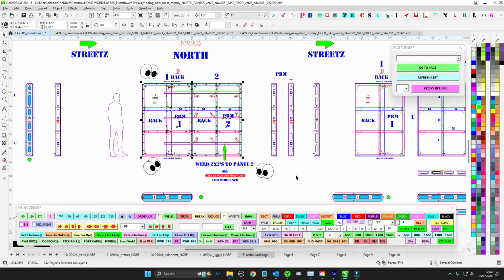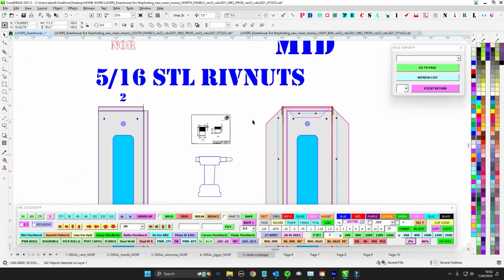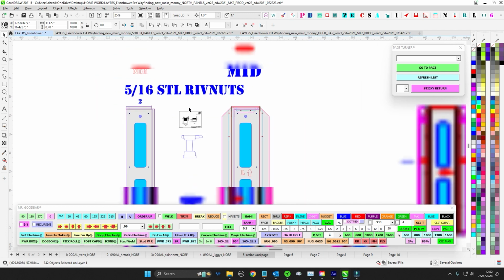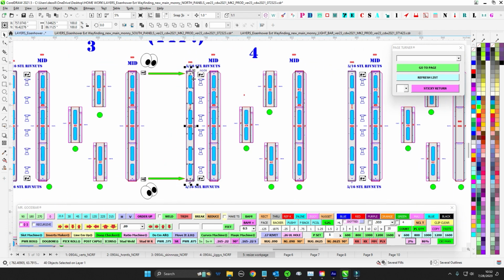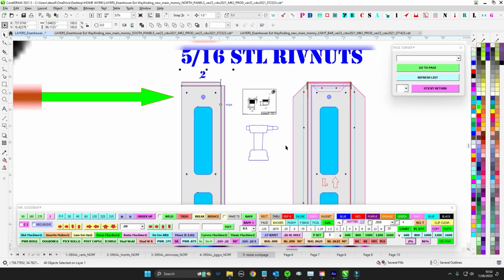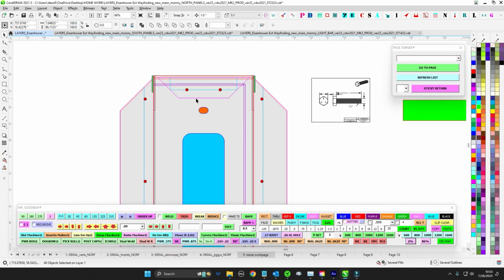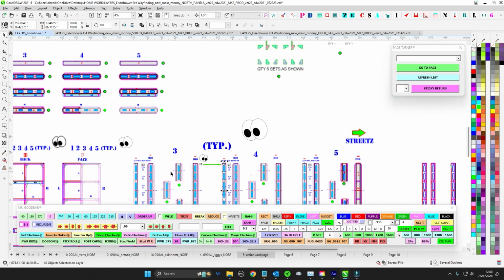It's not massive. It's a little less than your table. It's not going to be huge. They're only 6 inches wide. This brings me back to this. You'll see where there are RivNuts up top and bottom. So to rewind, go back to where you're riveting these together. When you put these together, you're going to RivNut through both the panel frame and here. That gives a 5/16 RivNut availability for a bolt to bring these together.